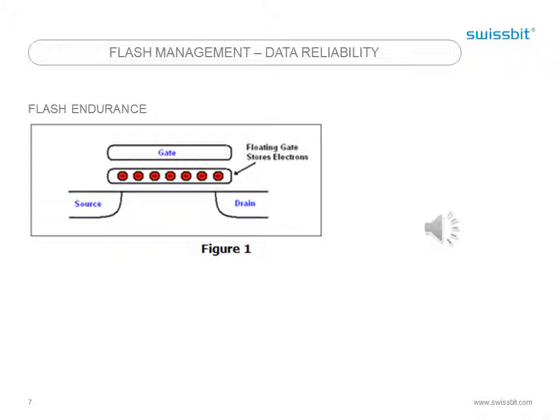An electric field, caused by a large gate voltage, Vg, is used to pull electrons from this conductive channel onto the floating gate. This gate voltage gives the electron enough energy to be pulled onto the floating gate. The number of electrons on the floating gate affects the threshold voltage of the cell, VT. This effect is measured to determine the state of the cell.